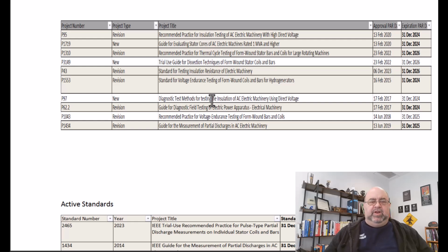Some of the areas I've been involved in is the impact of cable length on insulation resistance testing and how to respond to that. That stuff's in there. Then we also have absorption, desorption in there, and so on and so on. Somebody suggested surge testing in there as if it were a DC test, and it's not a DC test. But that's neither here nor there.